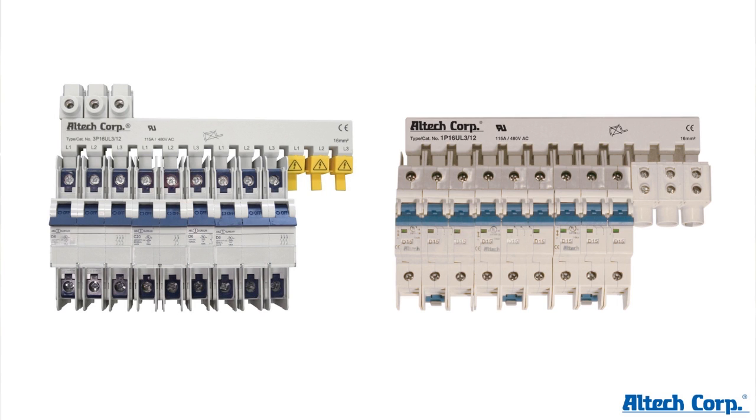Let me just add real quick that on our webpage we did a time test, if you remember, where we did the bus bar and then the daisy chaining. We did too good of a job at the daisy chaining because it's very neat. But after ferrules, stripping the wires, ferruling the wires, making sure your phases are correct, and tightening down on the wires to make sure they're consistent, compared to the bus bar where the phases are already done and the connections are going to be consistent.